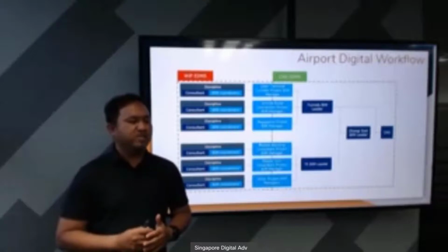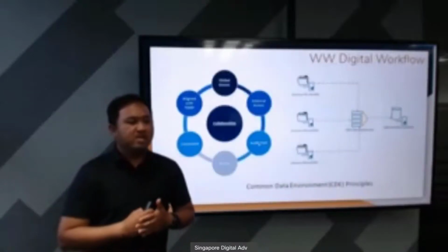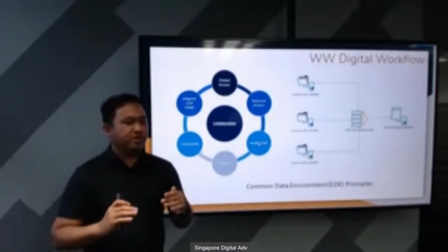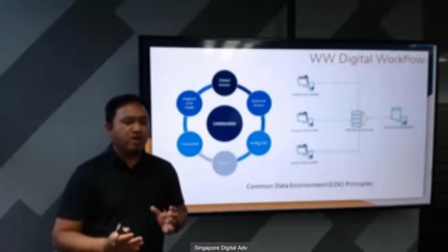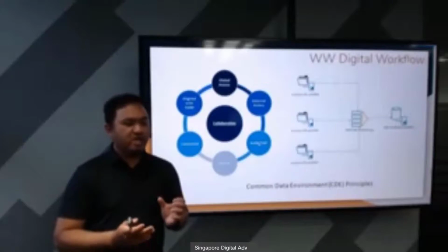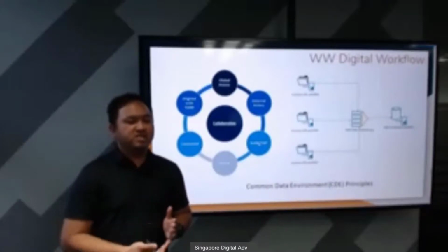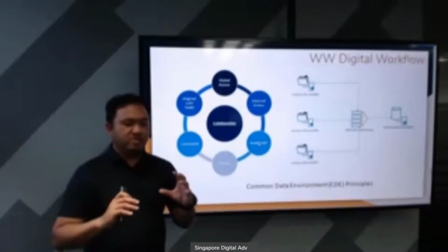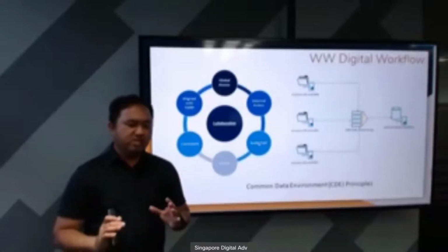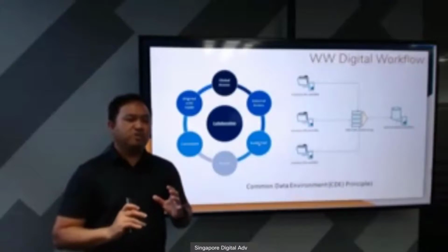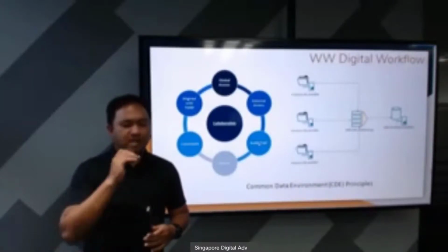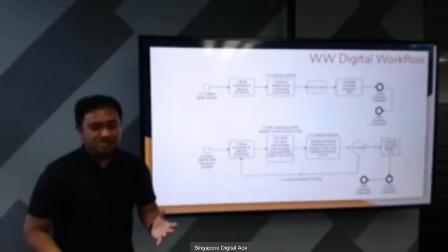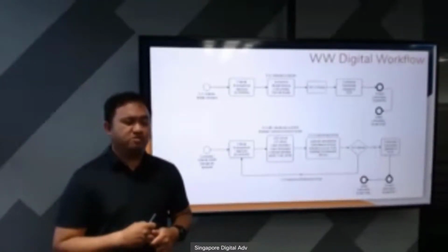So there's a distinct difference between EDMS and a CDE. In the current project that I'm working on, that is actually very, very clear. So an EDMS is just a portal where you actually upload models, and the actual workflow, who actually reviews it, who actually approves it, and who actually keeps it for future use, is inside the CDE, inside the common data environment. That is a big difference between a simple building project and an infrastructure project. You need to have a common data environment where you actually save and create a workflow for approval process of your models. It's a typical one. Another workflows that we are actually using now.